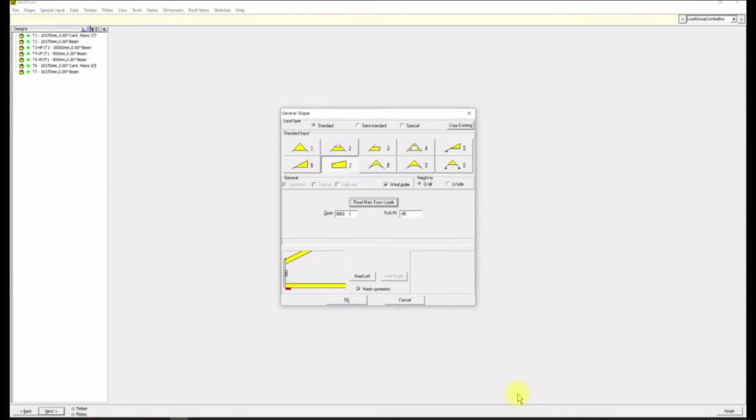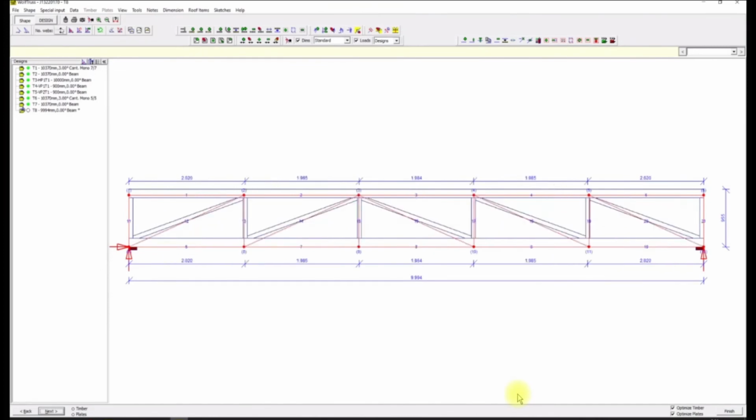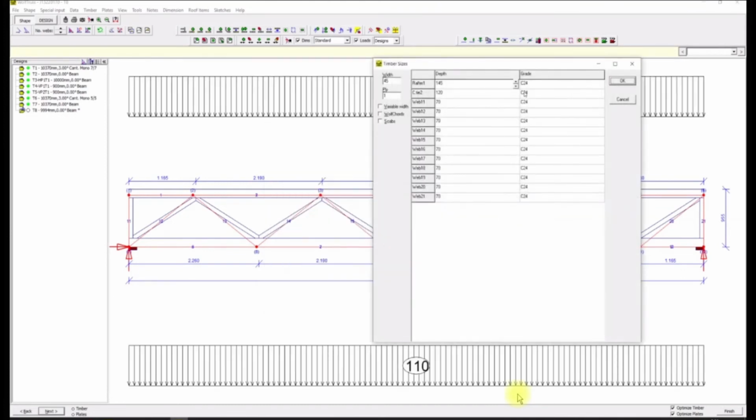When we have selected the truss and clicked Main Truss Loads, we can choose the truss from which this wind girder receives its load, and then additionally set the span, that is, the length of the truss, and the distance between the main trusses. Now we are adding the span and the height manually. Click OK, and there's your wind girder. You have to design it manually, like this one. We got the truss and now we calculate it.